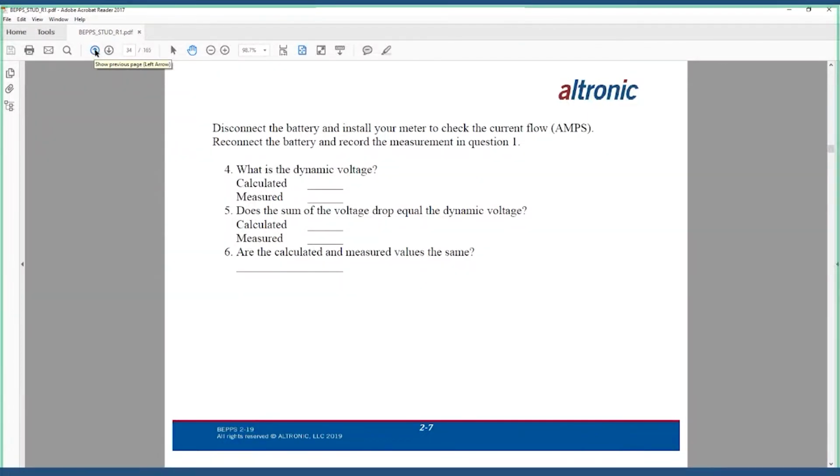Now a few things can get into the mix there. One, you got 12 students in a room using a 9-volt battery. Some of those batteries may only have 8 volts on them. They've been used, they've been in storage for a while, et cetera. So that's one factor. Another factor is the resistance of the wires that they use to build the circuits has to be applied to the calculations and theory of the whole overall circuit. And then the last thing is the value, the percent of efficiency of the resistor or the quality of the resistor.